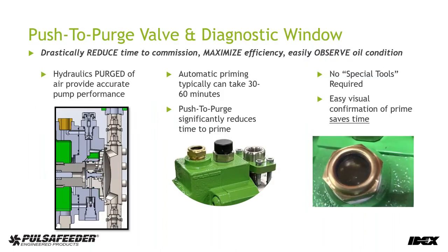So the push to purge valve and the diagnostic window. You may have heard me talk about solid hydraulics, but what's really important, super important, is that the hydraulics are solid, that there's no air in the hydraulic side. When I say hydraulic side, I'm talking about that area of the pump that provides the hydraulic fluid that drives this diaphragm forward and gives that process flow on the reagent head side.